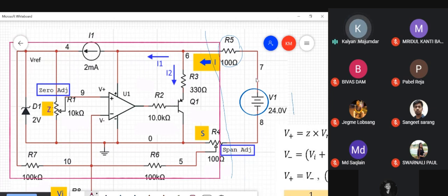So you have a power supply, you have an external load resistance. This load resistance could be an indicator, it could be any other resistor. And this circuit is supposed to act like a 2-wire circuit. Why 2-wire circuit? Because see, it has just 2 terminals. And the power supply is connected to these terminals, and your indicator or the output current happens to be the loop current flowing in this particular system. This loop current is the current flowing through the circuit back to the supply.